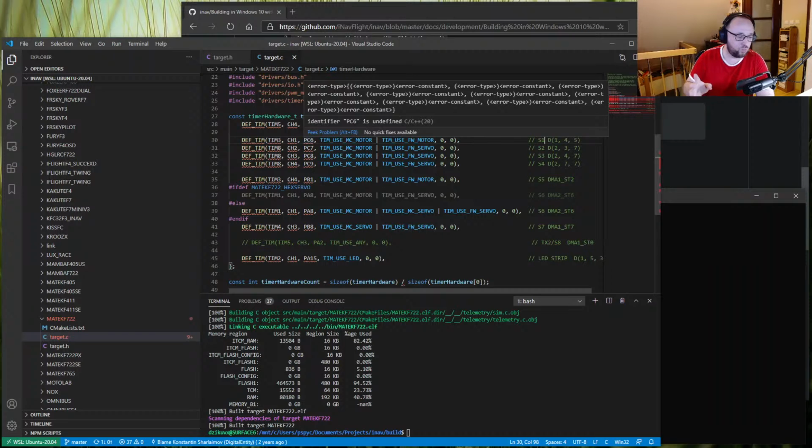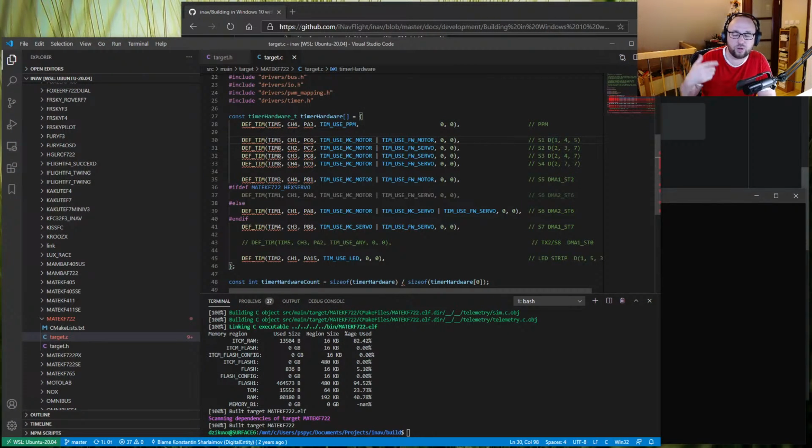If you want to find out which functions C6 can perform in the STM32F722, you will have to find the datasheet for the F722 MCU and check exactly what port C output 6 can do. From time to time it may be able to do, for example, serial or I2C or inputs of some kind or other functions, and then you will be able to map the pin into something else. But usually the outputs are organized in a way that it's really hard to reuse them for something else, and usually they are outputs. So this is the first one.